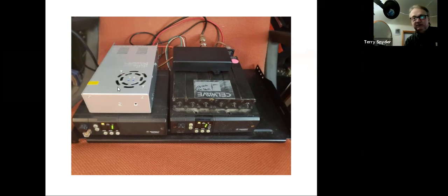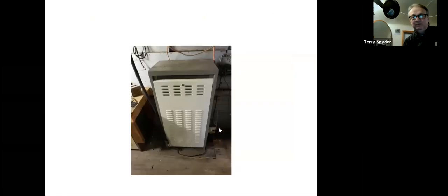And if you can find some radios at a hamfest that work, you can program them. It's good to have commercial stuff. You don't run them at their full output power though, because a lot of your ham radios are not made for continuous duty, meaning you can't take your microphone, click it in, wrap a rubber band around it and expect it to last more than about an hour before the heat overtakes it and shuts it off or burns it up. These are more continuous duty because this stuff is commercial, and they know that they're going to burn them up if they don't make them durable. This is what a typical repeater cabinet looks like.